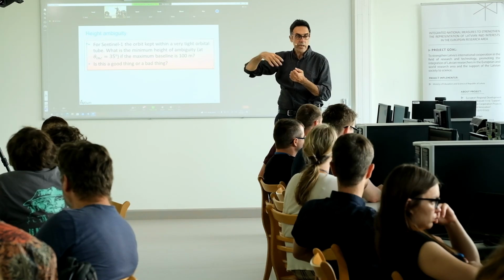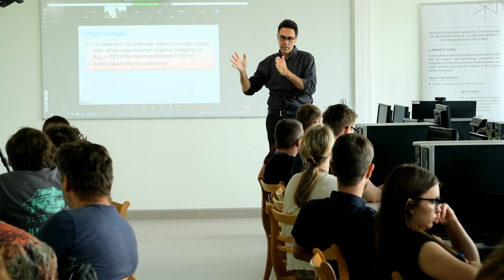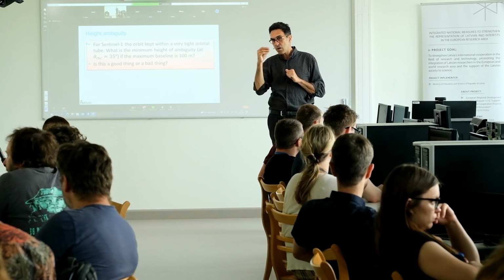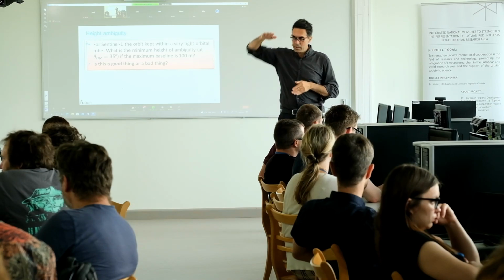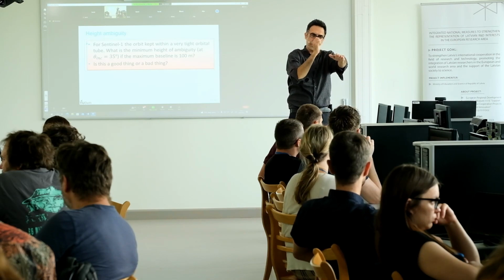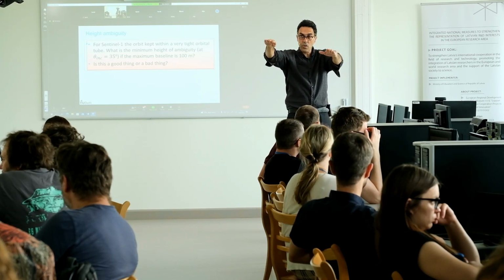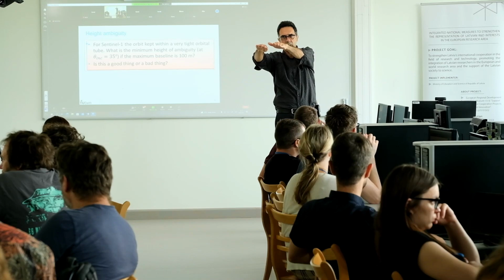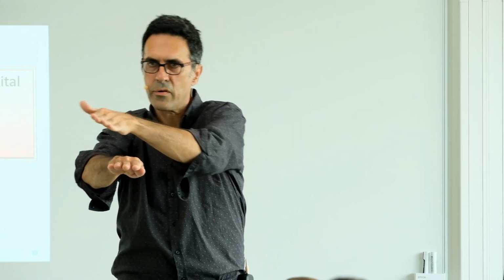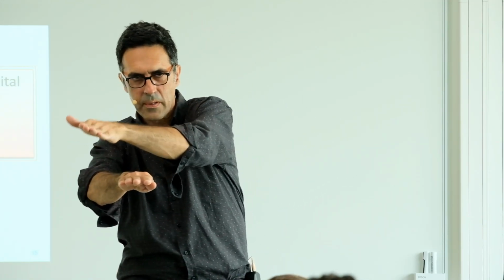But because of solar pressure and gravitational acceleration, the orbits drift. So this is why these satellites have little thrusters, as they call it, little rockets on board. So if the satellite is supposed to fly here, and now after a couple of weeks it's flying here, they fire the thrusters with a little bit of cooled gas, and it's slowly going to drift back to the nominal orbit. And actually it's going to drift further, and all the way until it's here too far out. And then they will fire the thrusters again, and then it goes back. So basically, it's like a drunk driver on the road, right? It's trying to keep the zigzagging, but trying to stay on the road.